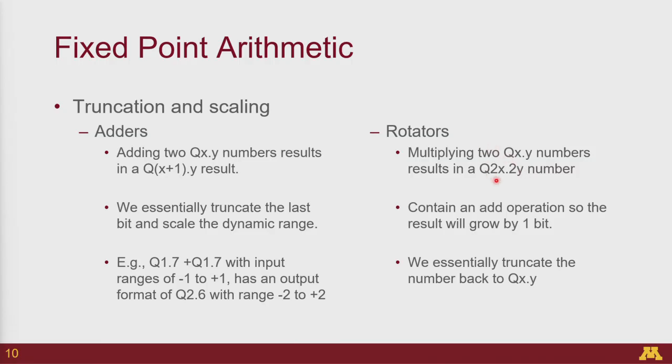So essentially you would truncate the MSB x bits and the LSB y bits. This only works if we started off with the assumption that everything is between the +1 and -1 range. If we worked, for example, with integers, this would not hold good anymore.